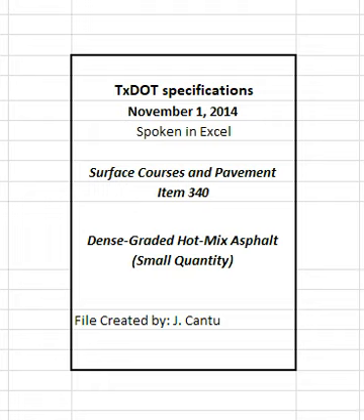Post-manufactured RAS is processed manufacturer's shingle scrap byproduct. Post-consumer RAS is processed shingle scrap removed from residential structures. Comply with all regulatory requirements stipulated for RAS by the TCEQ. RAS may be used separately or in conjunction with RAP.